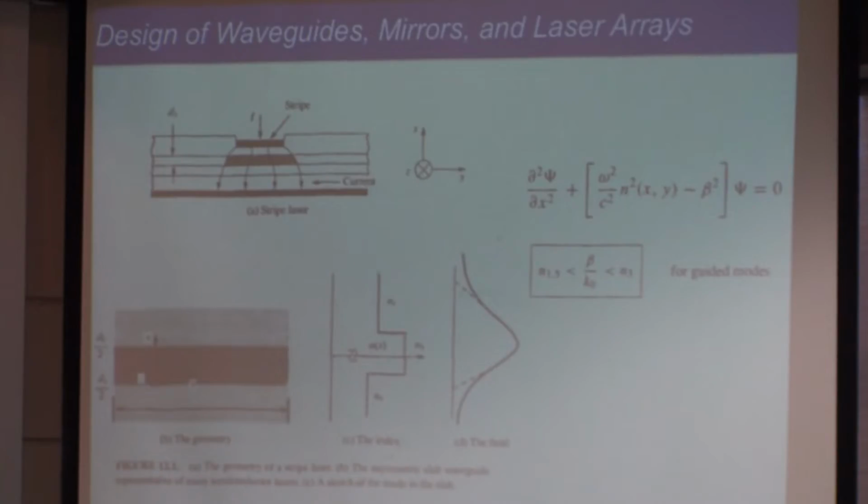And that's a rudimentary way of shaping the flow of light to get it to go in the directions you want, such that it hits the mirror and gets reflected and you get gain again. Or rather, you get lasing. I mean, gain you can get by injection of current, but lasing needs feedback. So the mirrors give you the feedback.